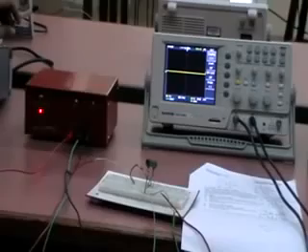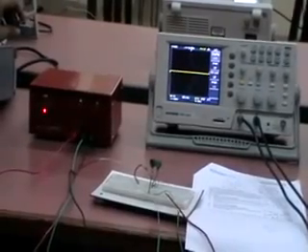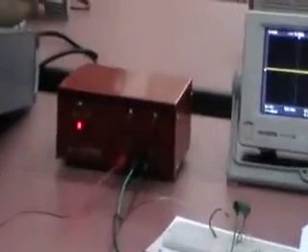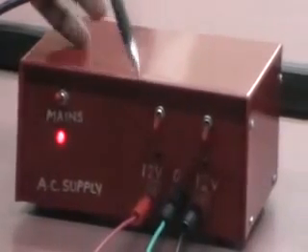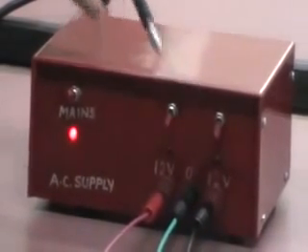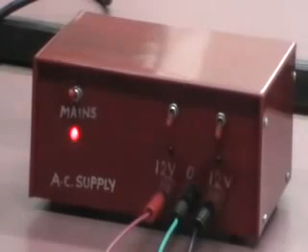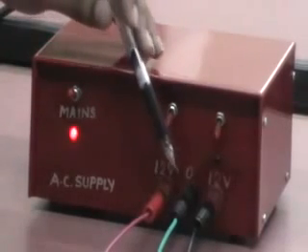Coming to the new component in this rectifier part, it is the AC step down transformer. This red box is the step down transformer. We will have different switches across here. This is the 230 volts. A signal will be produced with 50 hertz frequency. The output will be 12 volts.